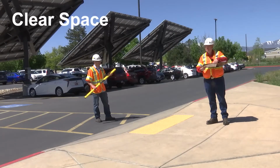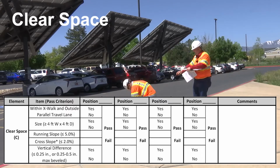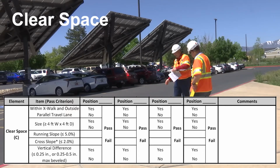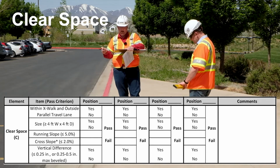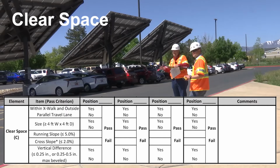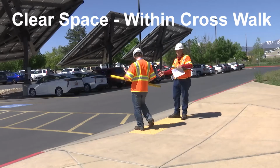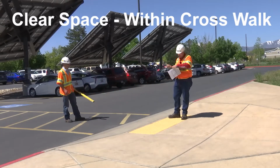Next, we'll check the clear space of this ramp. The clear space goes from the flow line of the curb and gutter, and it extends out 4 feet, and it is the width of the curb cut. So we will take the running slope, the cross slope, and we'll make sure that the clear space is within the crosswalk entirely and outside the parallel vehicle travel lane. So first off, we can verify the clear space is within the crosswalk, so we're good there. And we'll take our measurements.